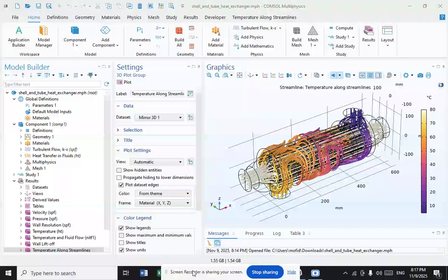And what about the regenerative type? A heat storage medium temporarily absorbs heat from one fluid and then releases it to another fluid. A common example is a thermal wheel in a HVAC system that captures heat from exhaust air to preheat incoming fresh air.